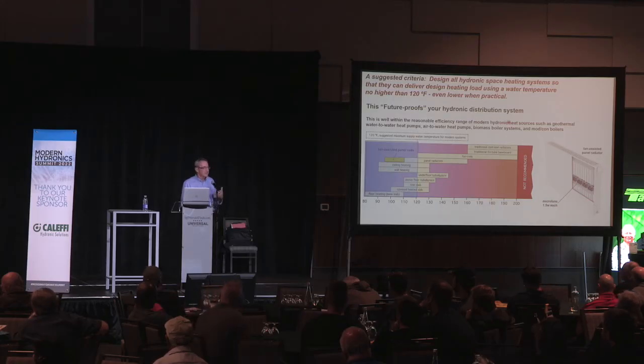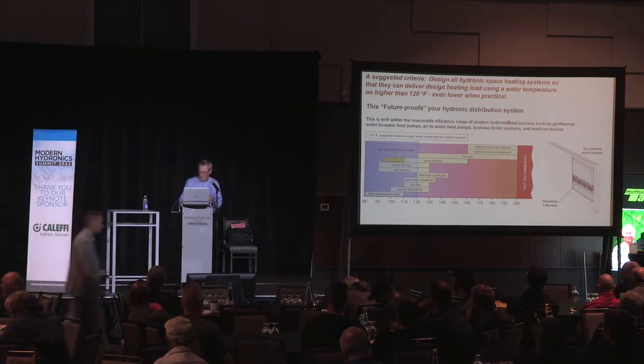Be careful about doing things like what I call plateless staple-up. Now, I'm not going to ask for a show of hands of who does plateless staple-up, but you won't find that in other markets. You won't find that in Europe. They understand those aluminum fins are important to transfer heat laterally away from the tube. Systems like that, to get reasonable outputs, need pretty high water temperatures. And that's floor heating, but it's not really floor heating that's compatible with where we're going with energy sources.